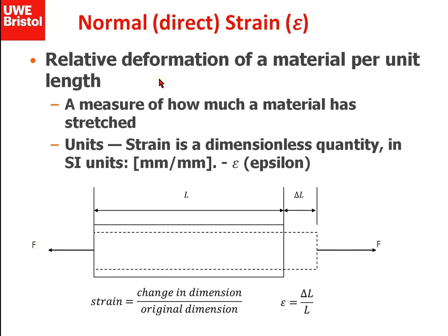We can say, let's look at the strain that's happening. For my small bar with the small elongation and its small length, divide the elongation by the original length, and compare it to the long bar, which is going to have a longer elongation because it's got more material that you can pull apart, divided by its original length. You're going to get the same values. So we've taken away, if you like, the effects of geometry on our problem.